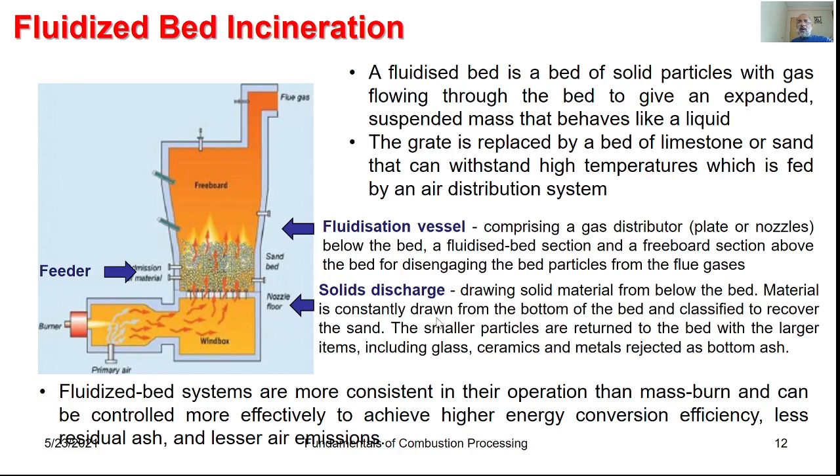The material is constantly drawn from the bottom of the bed and classified to recover the sand. The smaller particles are returned to the bed, with the larger items including glass, ceramic and metals being rejected as bottom ash. These kinds of incinerators are very consistent as far as their operation is concerned as compared to other technologies.